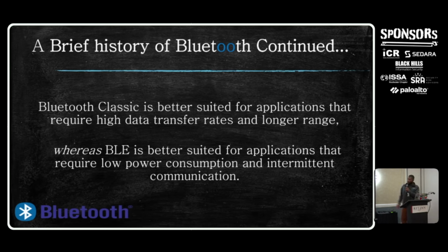Another thing about Bluetooth that I'm sure a lot of you are familiar with is that in terms of the wireless spectrum, it uses the same exact frequency range as Wi-Fi, starting at 2.402 to about 2.480 GHz. Part of the issue with Bluetooth in terms of interference between signals is that it'll do something called frequency hopping. Essentially there are 3 advertising channels and 36 data channels.